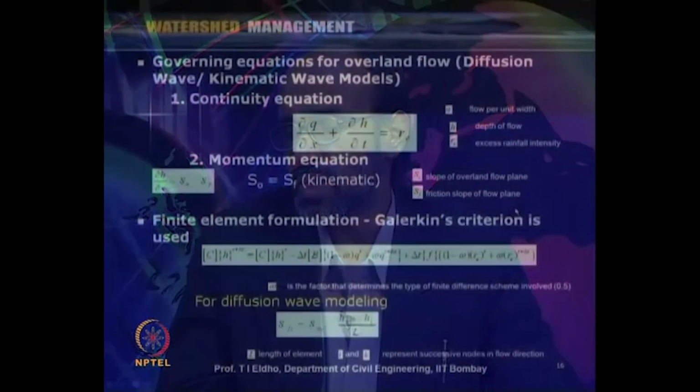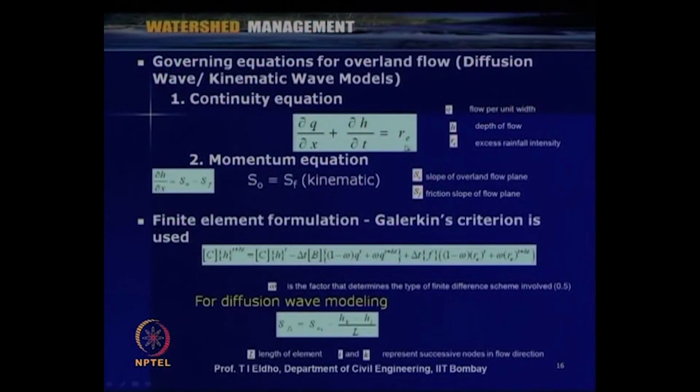Here we use the finite element method to solve the governing continuity and momentum equations. The earlier equations we considered were the full form of the Saint-Venant equations, but the diffusion wave and kinematic wave are simplified forms of the dynamic wave or Saint-Venant equations.